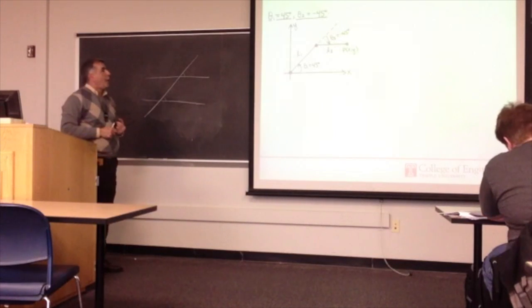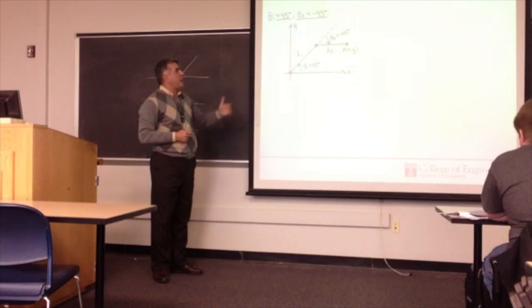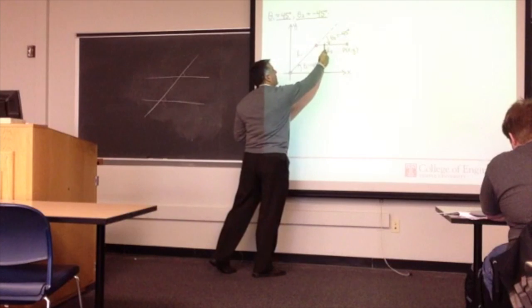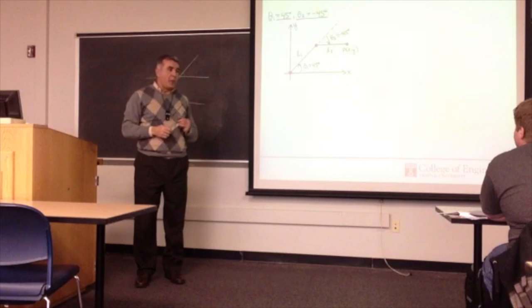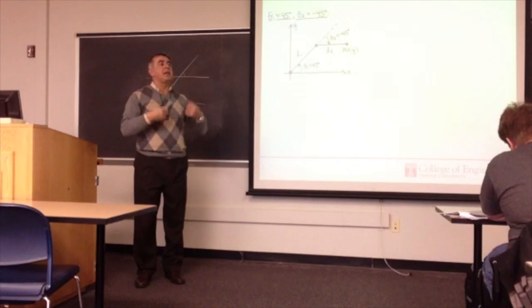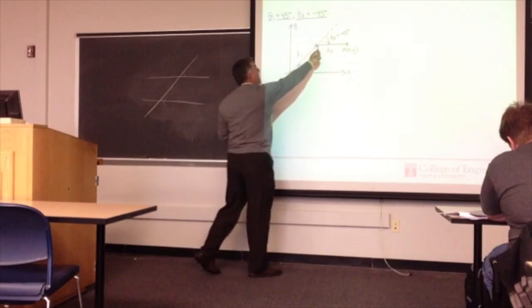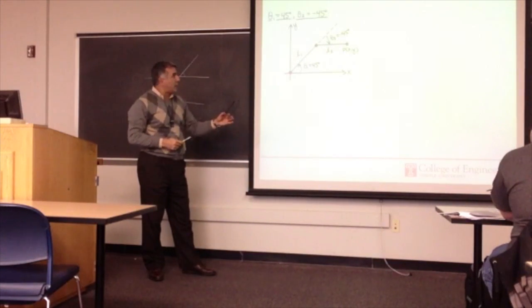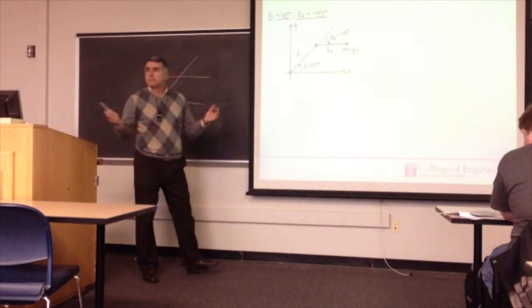Now, theta 1 is 45 degrees and theta 2 is minus 45 degrees. Why is theta 2 minus 45 degrees? Yes, the elbow is down. Exactly, and it is because it is in the clockwise direction when you are measuring it. The movement is in the clockwise direction. So theta 1 and theta 2 are now known.